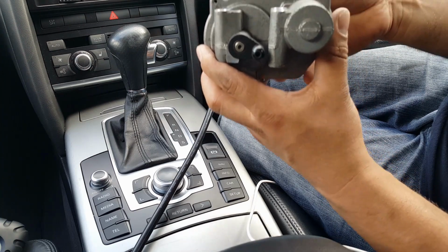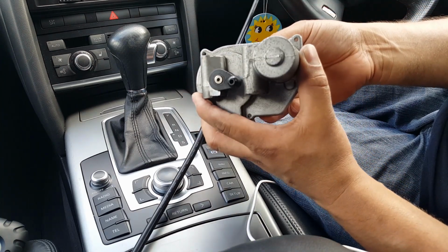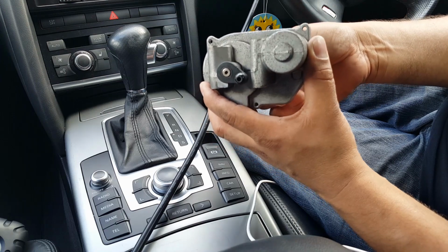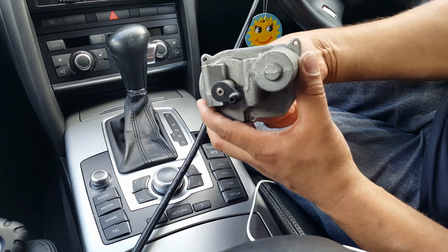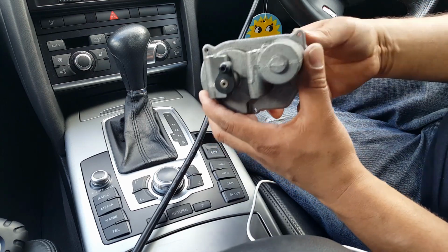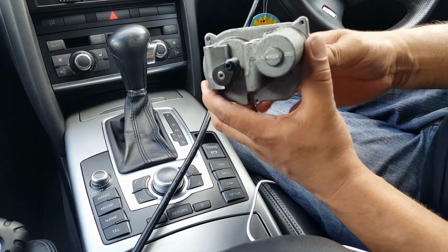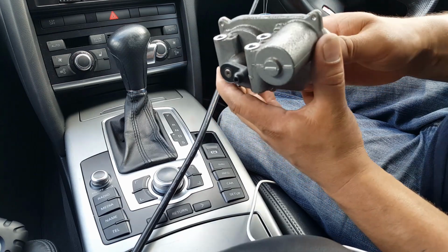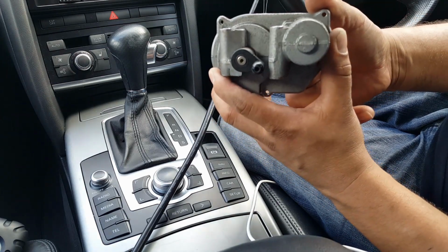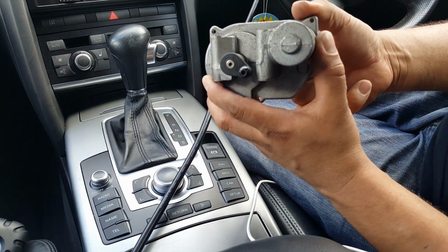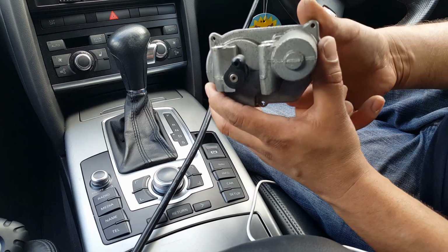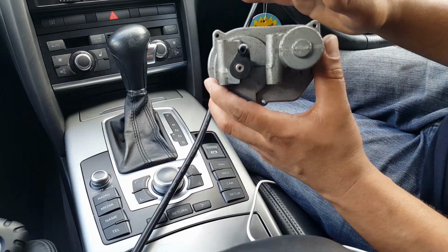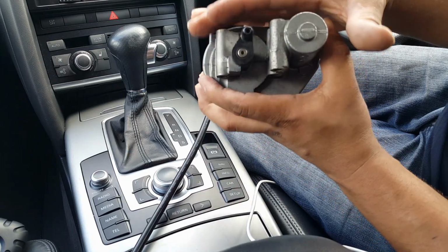What it does is, because the manifold is worn, it moves a little bit further, and the ECU detects that further movement, and it just rolls all the way back, and then it does the same again, goes all the way down. Let's say, for example, it should stop here, but it goes a little bit over, and it detects that little bit over, and it goes, no, that's wrong, and comes back and deactivates the actuator.